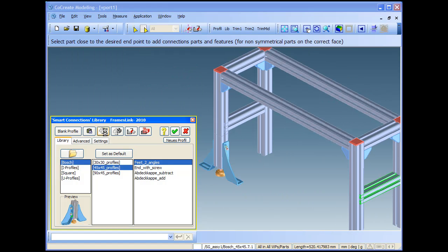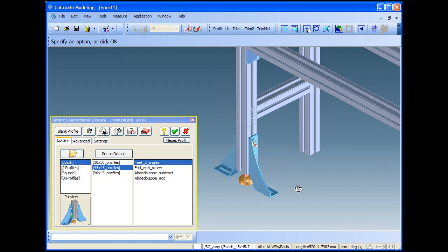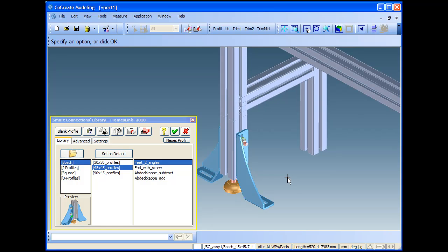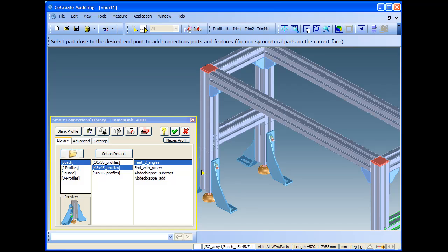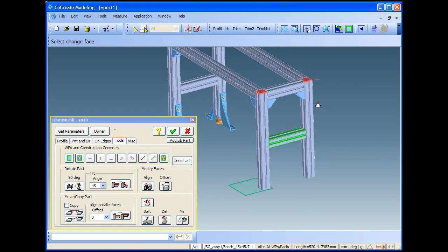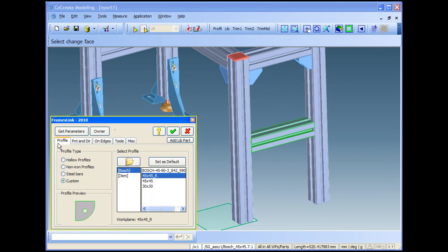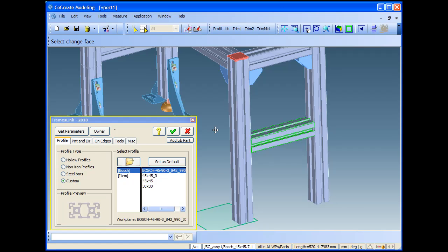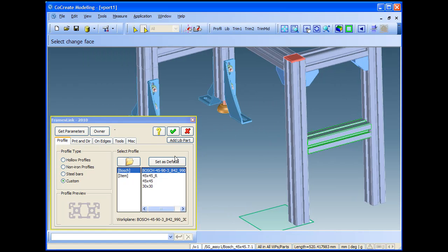And here another example, as you see, I select the feet, and the profile as well is shortened on the bottom, and the feet parts are added automatically. I can rotate them before uniting. Okay, and here maybe I want to add a bigger profile just to show you that profiles can be combined as long as they are fitting to each other.